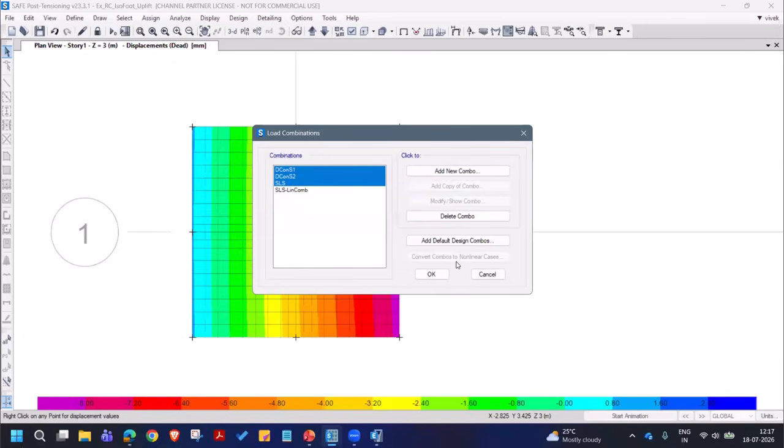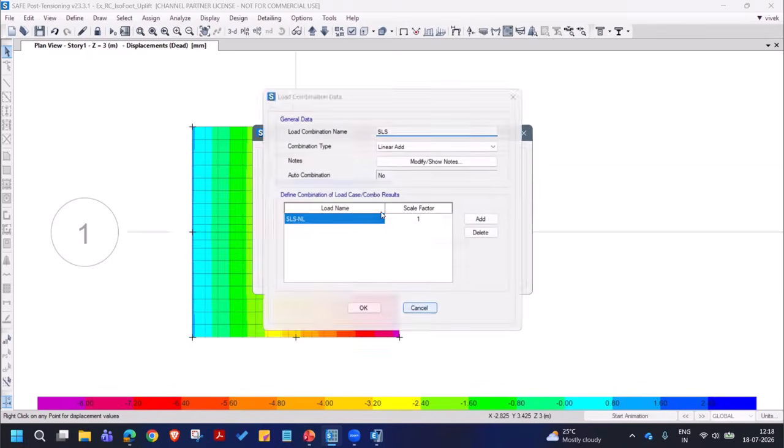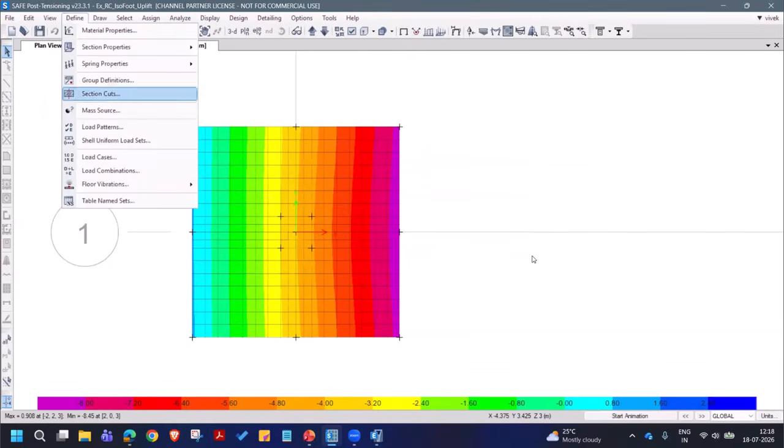So when you, for the first time, perform the analysis with a linear basis, you'll be able to see the uplifts, tension, or the positive pressures in the soil pressure output. Then you'll have to perform this, right? I kept one linear combination just for comparison. The another one is for nonlinear case. Now program converts this into nonlinear case.